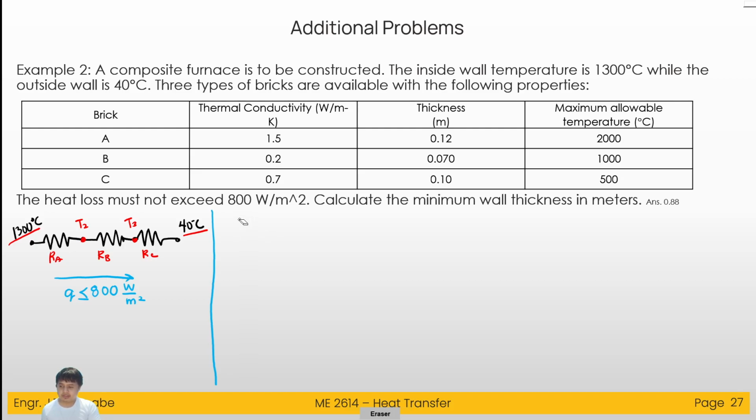So to find the temperature, no? You have Q equal to delta T over R, basically. This is the simplified formula. So this Q here, we're imagining this is a single node, so let's say this is QA, this should be equal to QB, and this should be equal to QC. Okay?